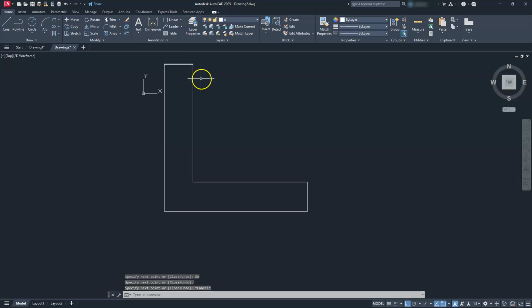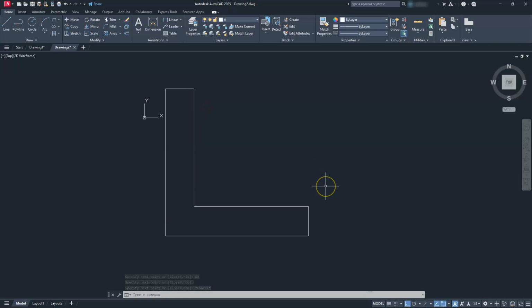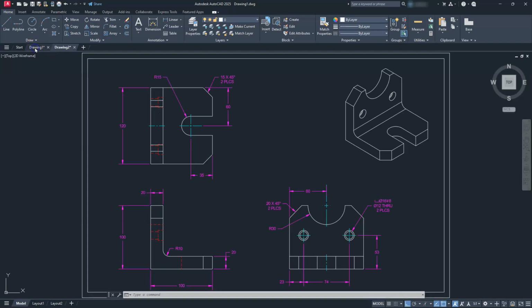Okay. If we refer back to the drawing, remember we had two different chamfers on there, and I'll switch over to the drawing here in a second. That's going to play a super important role in figuring out where these lines are going to show up that display the edges. Jumping over to the AutoCAD drawing of it, you can see that here at the top I have a chamfer that's set at 15 by 45, and on this side I have one that's set at 20.